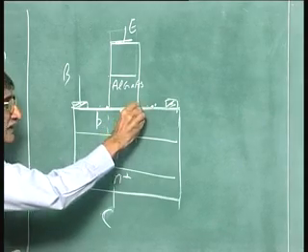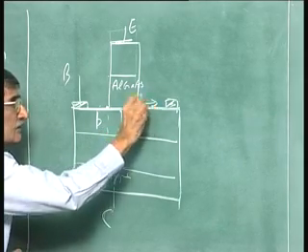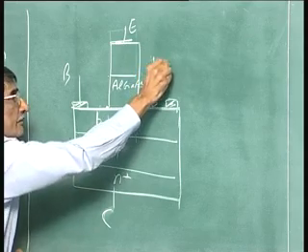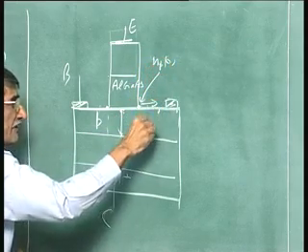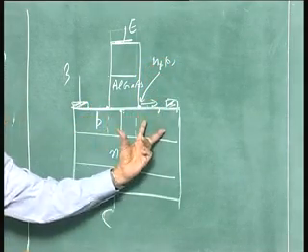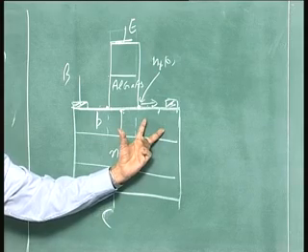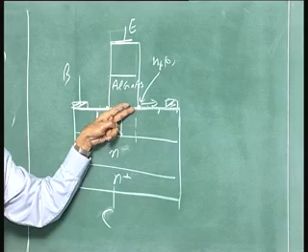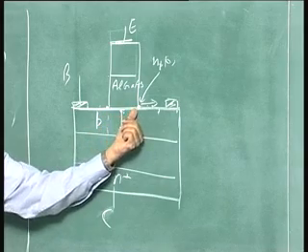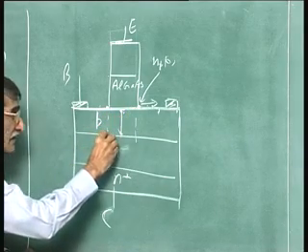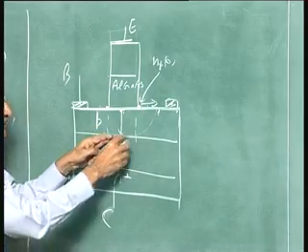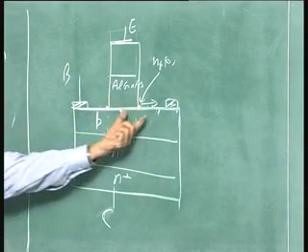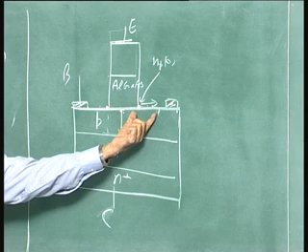Similarly, if you take it here, that quantity is N_P0, and up to a width equal to W_B, practically it decays from N_P0 to 0. It is a boundary condition here, and if you see the equi-carrier concentrations, if that is 0, that will be 0 there. So, this is W_B, the base width.